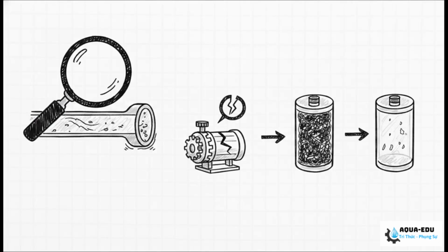But listen, just staring at the membrane data isn't enough. You've got to play detective and look upstream. Are we accidentally creating our own problems? First thing, calculate your Langelier saturation index, or LSI, right in the reject stream. If it's creeping above -0.2 and your antiscalant dosing pump has lost its prime, congratulations, you are actively manufacturing calcium carbonate scale. Next, double-check your feed turbidity.